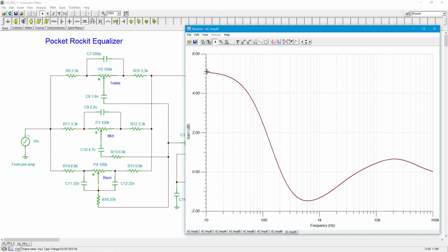All right. So we've got a nice boom at the bottom, a little scoop out here in the center, and then a little bit of a rise to give you a little bit of attack and edge. And then, of course, here's your 20 kilohertz. This doesn't really matter, it's outside the range of human hearing. So you really only care about this section right in here, right? So you've got like 5 dB of bass boost, a couple of dB cut here in the mid-range, and then another dB or so rise at the very top end, right? That's not an extreme bit of EQ.